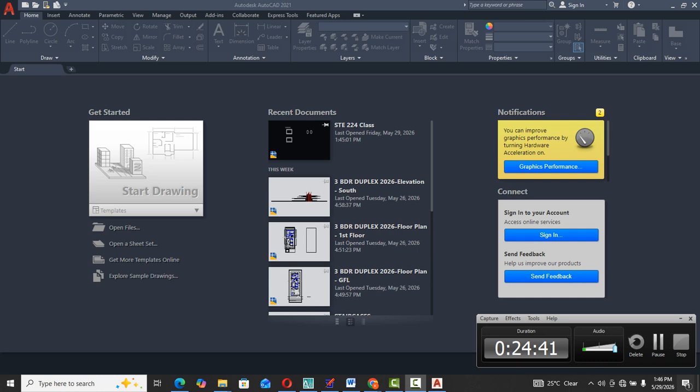All right. So if I want to do offsets, the advantage with using polyline is that I select offset. It tells me to offset. You see the command. That's why this is what is called AutoCAD command. You follow the command to get all that you want done. So offset, specify offset distance.